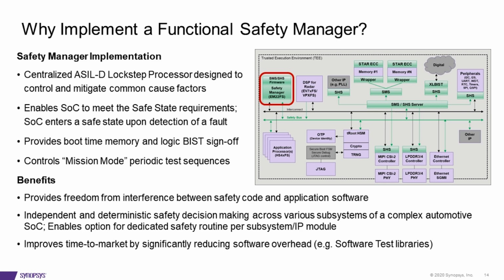Like I sort of alluded to, you may have areas of the SoC that are more safety critical than others. So you may decide that if there's a fault in a certain area of the device, say a subsystem that's managing a more critical safety-related aspect of the device, then that escalation may warrant that the device has to be reset.